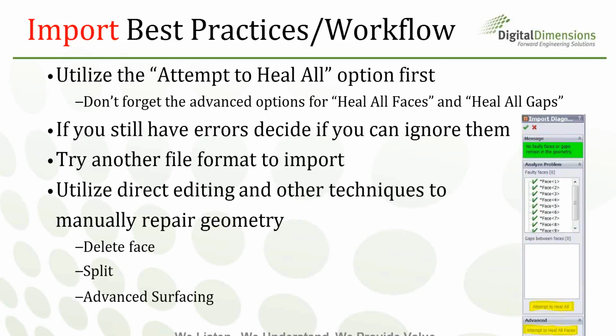Those are things like delete face, splitting apart, and then you get into some advanced surfacing techniques if you're trying to repair some complex geometry on those faces. So just be aware that those options are there in direct editing if you have issues and you actually need to edit the part. It'll still save you time to bring in the 3D geometry and just make the corrections to it.